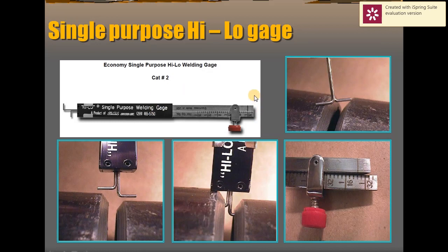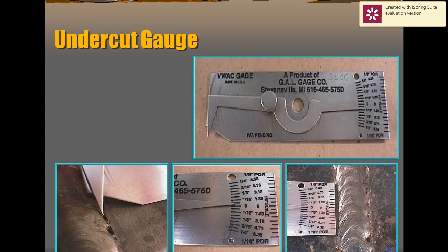Various positions are given for the Hi-Lo gauge, with an equal surface appearance. In these images you can see the variations: one pipe is in an upper position and one pipe is in a downward position. So deviations come, and if we conduct the experiment like this, the weld bead will vary and affect the quality of the product. So before conducting the experiments, with the support of various gauges, you have to ensure and confirm. Only after that should you start the operations.